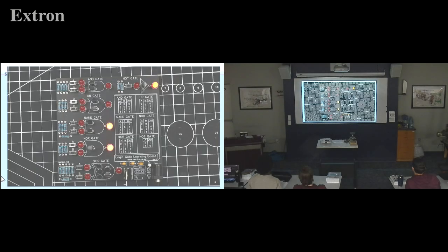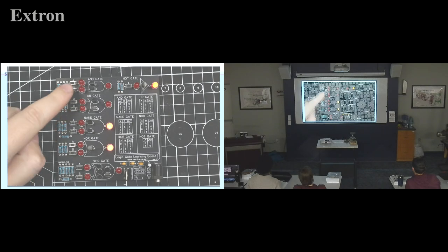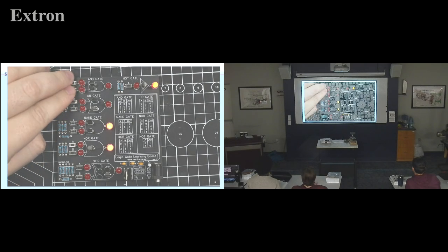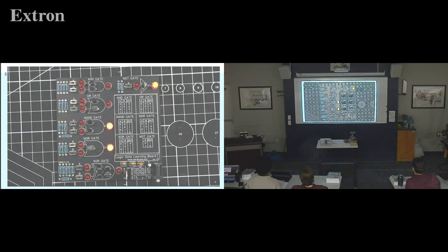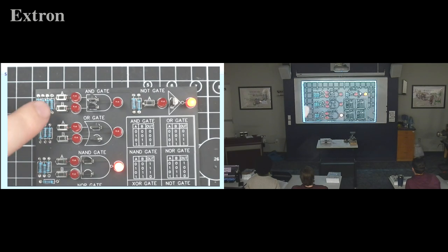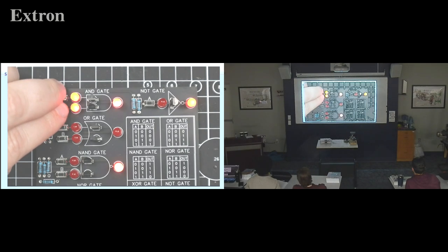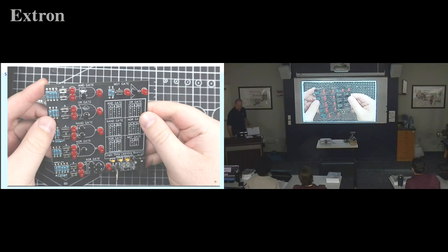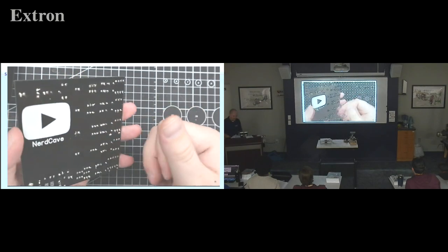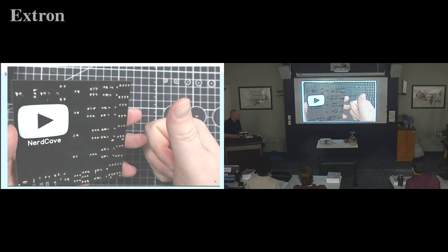Here is the finished project, the $3 board that you can use to teach your students about the different types of logic gates. All the inputs are currently 0 on this board unless the button is pressed to allow current to flow to the gate of the transistor. Giving this board a quick test and comparing them to the truth table, we see everything is working as it should.